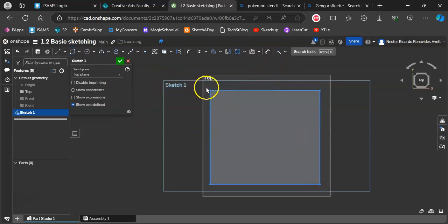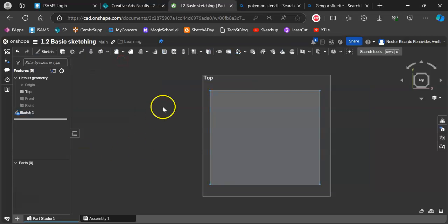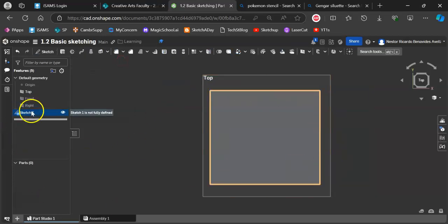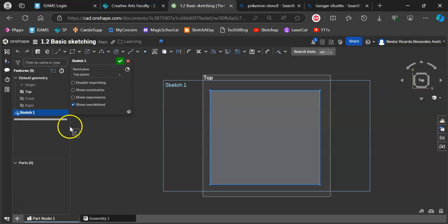First bit I need you to understand is if you select the rectangle, in this case the line is blue and you finish your sketch, it looks like this when you finish the sketch, right? But it is a visible line, so that means if you're laser cutting it or you're 3D printing, it will cut or print over that line.